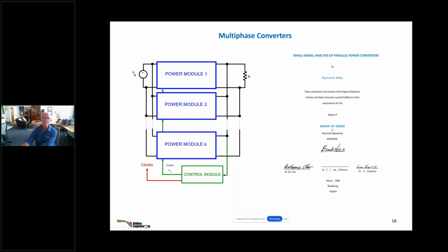So 40 years ago, the demands were actually much higher than they are today on processors. Today, they only need 1,000, 2,000 amps. That's like nothing at these voltage levels. The other thing we did that was kind of unique is that we had 380 volts coming into a phase-shifted full bridge to give you that 7,000 amps directly. There was none of this intermediate bus stuff and then a point of load converter. This was done with a great big bulk supply. Fairly close to the CPU, but very similar to what we're doing today.